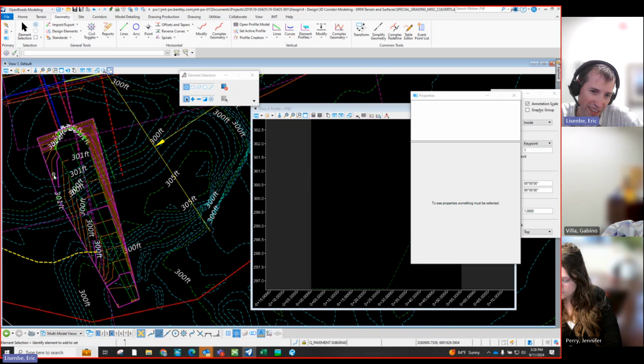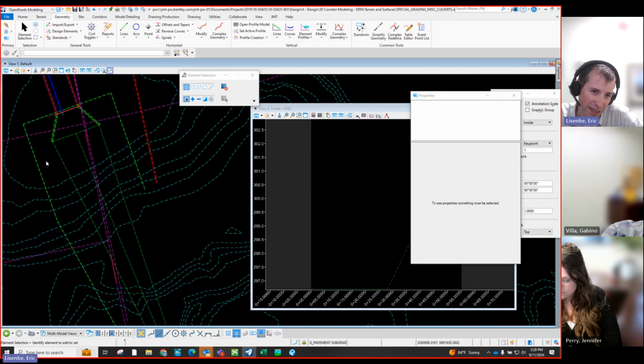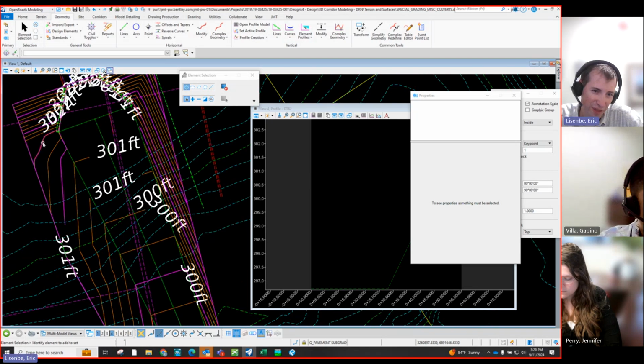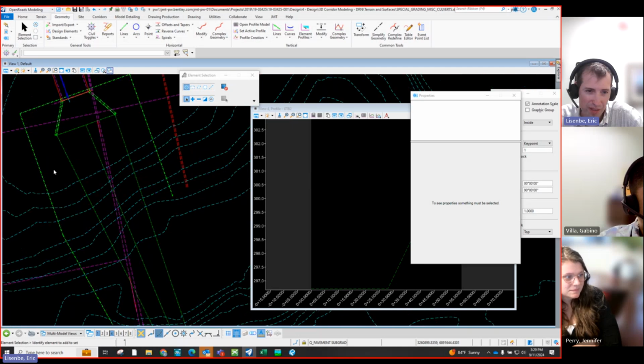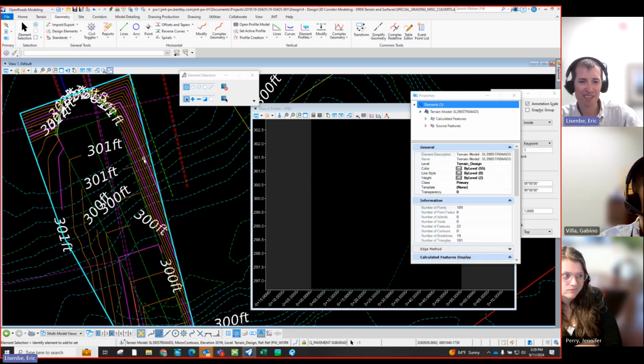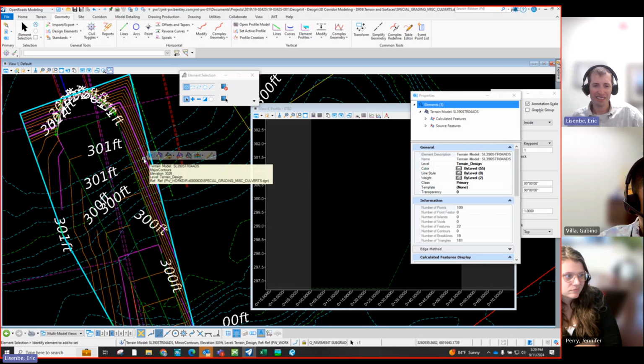That's the bad thing about GeoPak. You just load it from a TIN, and then I could kind of smooth that out, and then I'm just giving them a point table. But here, I don't think I can really modify the contours it spits out, and I don't think you can really just plop them in as hard elements. At least I haven't figured out a way to do that.